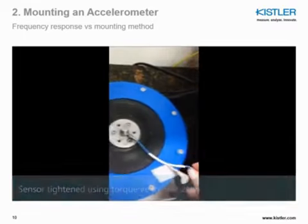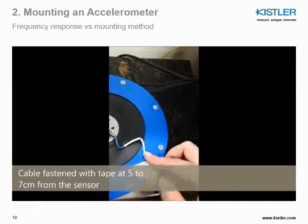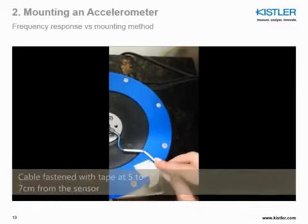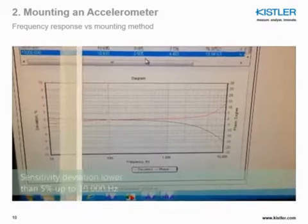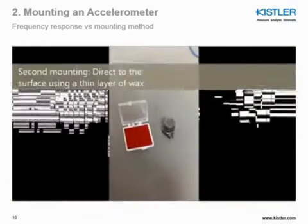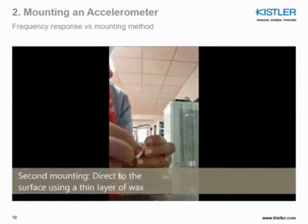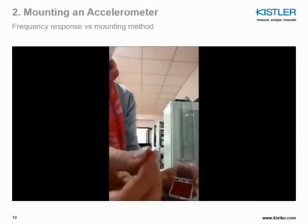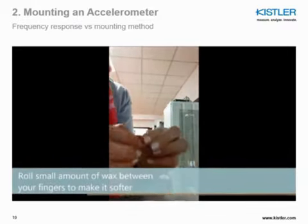Then we will mount the sensor onto the shaker and fasten it using a torque wrench at 2 Nm. Then we will mount the cable on the sensor and fasten the cable as shown here. Then looking at the frequency sensitivity deviation, we can see a 5% deviation at 10,000 Hz.